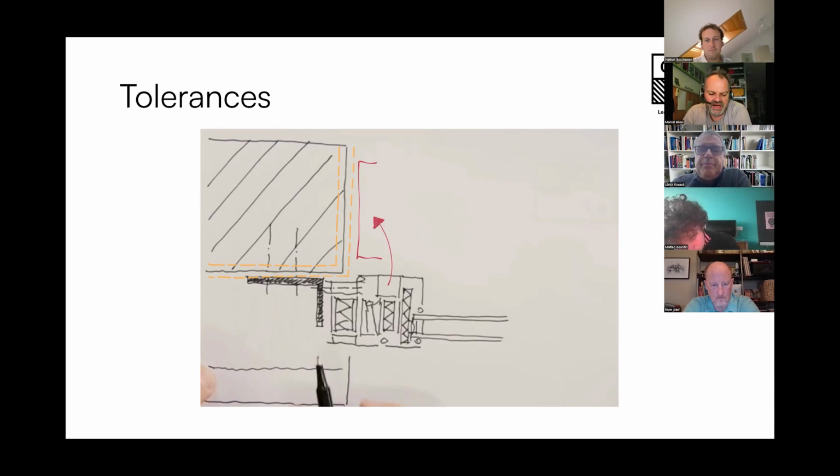Usually, when you have it behind, within the layer of insulation, you can still move it in and out a little bit. It depends a little on what the overall view from the outside would be, but make sure in this case that you have measured everything. Maybe the most common is that the smallest opening in the structure defines the size of the windows, and then you can bridge bigger gaps. That's the right approach, in order to make sure that it fits.